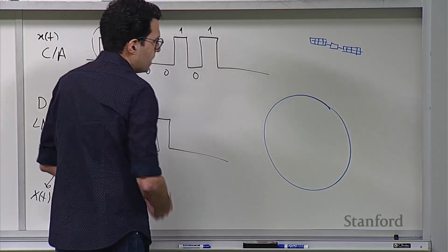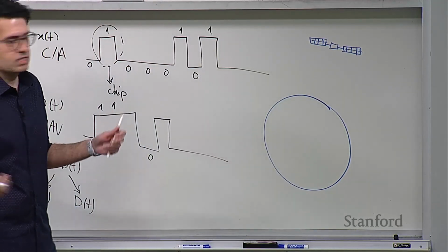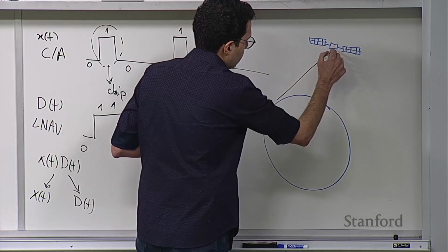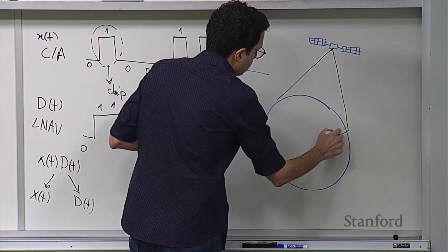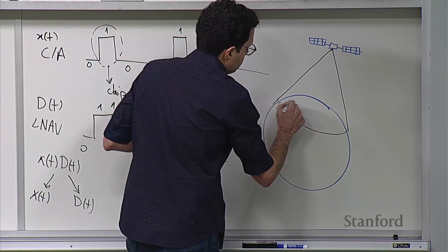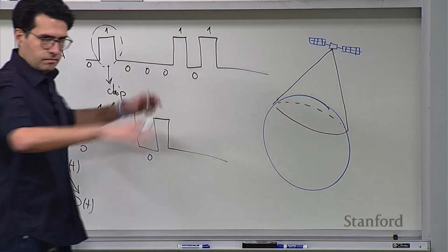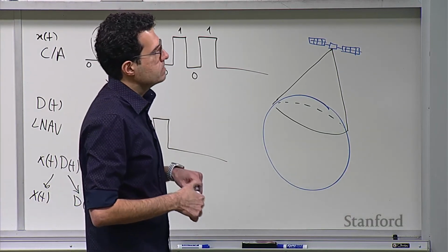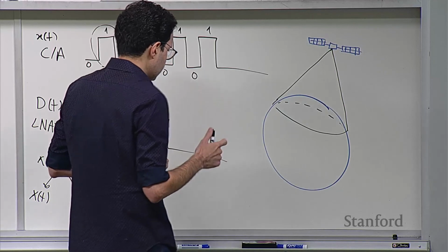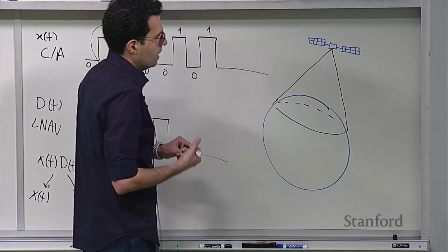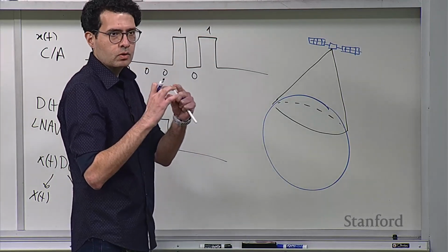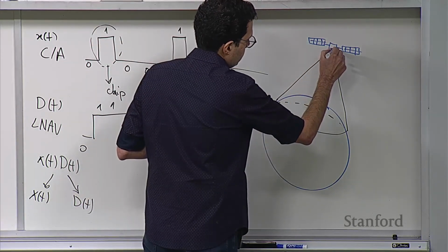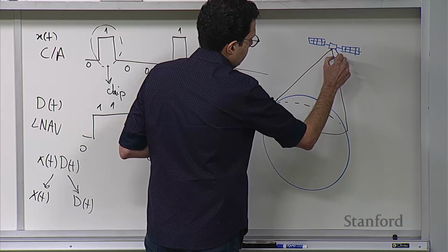Generally, the antennas they have, because they want as much coverage as possible, have super wide antenna patterns that cover as much of the Earth's surface as is visible to them. So they have very wide patterns. Now, what they did with the Block 3 satellites for the M code is add an additional antenna which can transmit a much tighter, localized beam just for the M code. So it's almost like a separate antenna that does that.